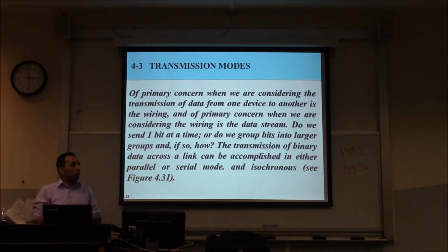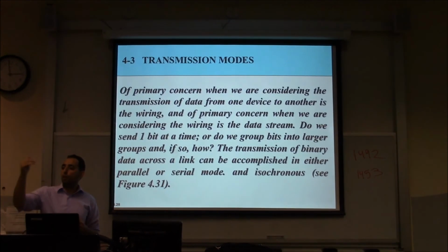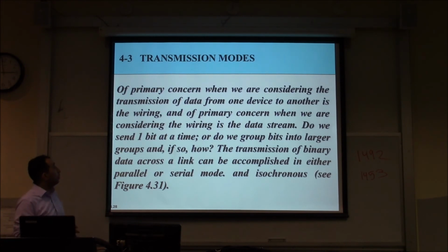So for example, when we have a long distance communication, we try to use one of the techniques that we mentioned here that has the lowest bandwidth. For example, AMI, as we saw, uses only one signal element. That means it has lower bandwidth, right? So we can use it for long distance communication, but we cannot use it without scrambling. Long distance communication without scrambling will make no sense to use AMI. So we add the scrambling for AMI. Now we can use it for long distance communication. Next part of the class here, we want to talk about different transmission modes.